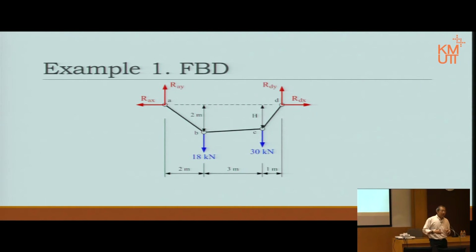Well, here's the hint again. At this part of your learning curve, we are not going to have more unknowns than equations. You just have to figure out another free body diagram to help out, similar to the structure with the pin connection. If we think about it, this is kind of like a truss, because all connections are pins and all load is at the joint, not on the member. So the idea is similar to a truss.